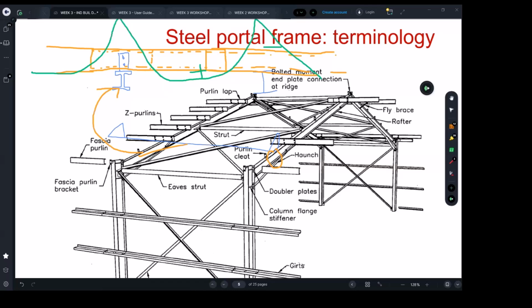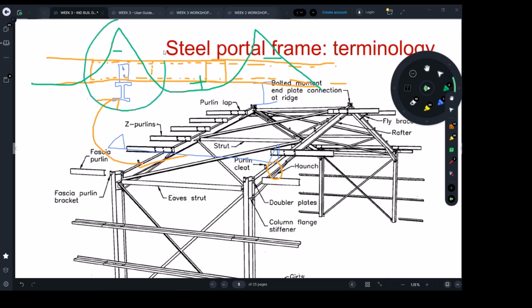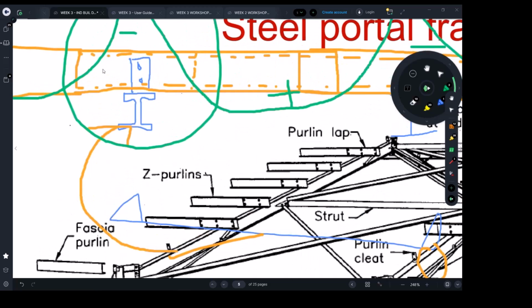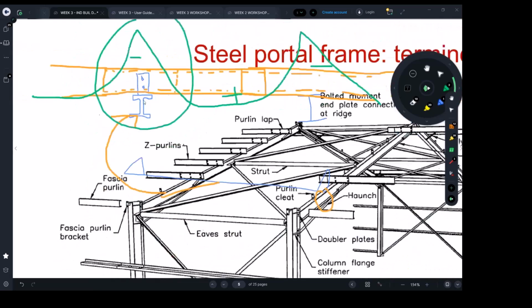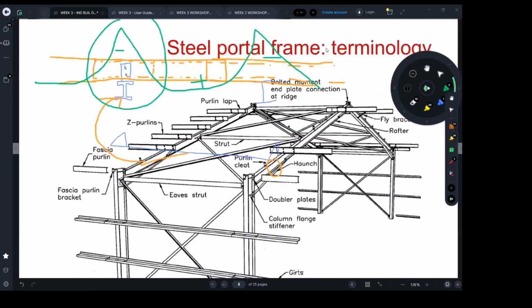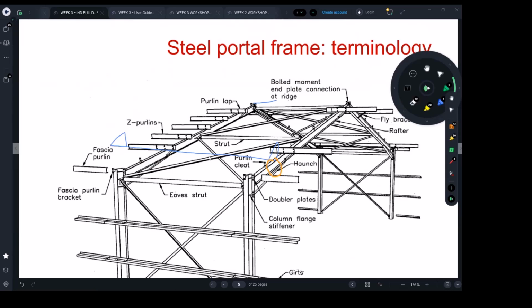Joe Mace. Yeah, so the bending or flexure on the purlins is basically negative above the supports. And when it is negative above the support, as I said to you, the forces are typically higher. That's why it's going to be an advantage to have 2 members lapping to each other at the support. So you link the design consideration with the construction consideration, and it helps engineers to know what to check and verify when they plan the building of things like this.